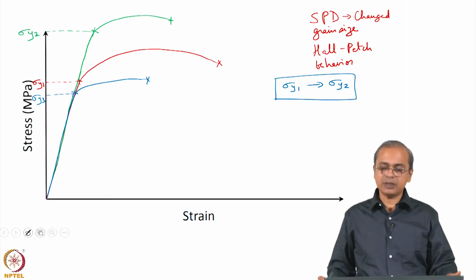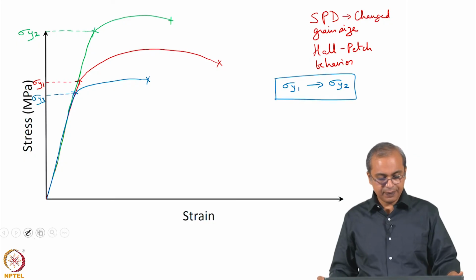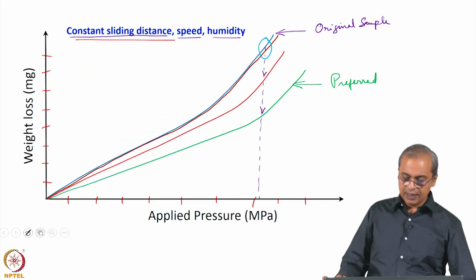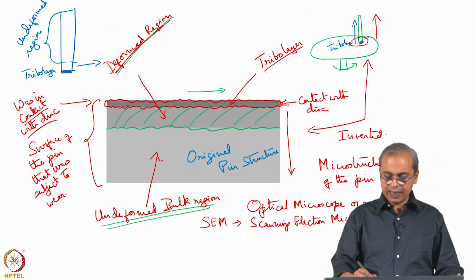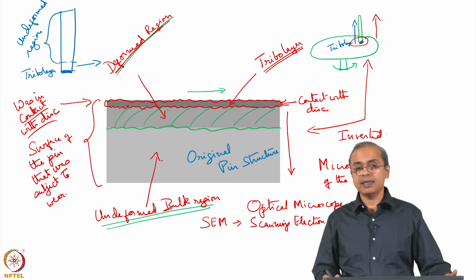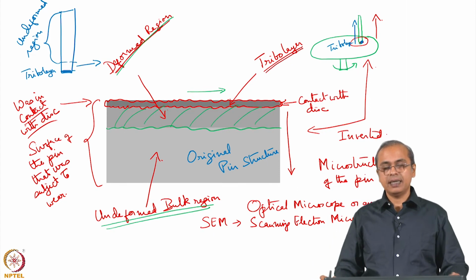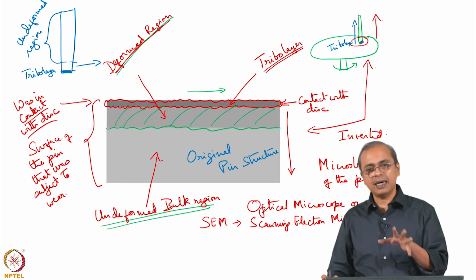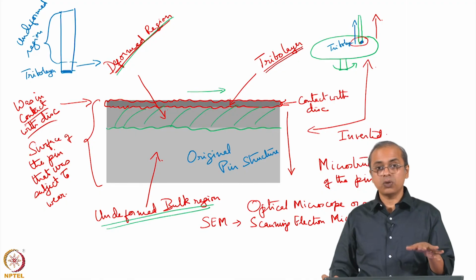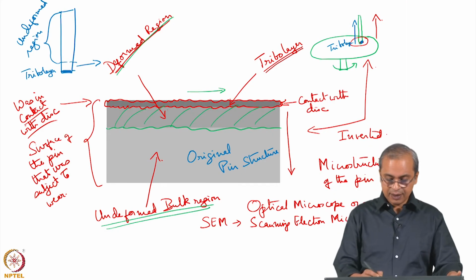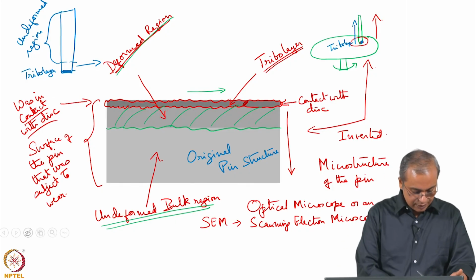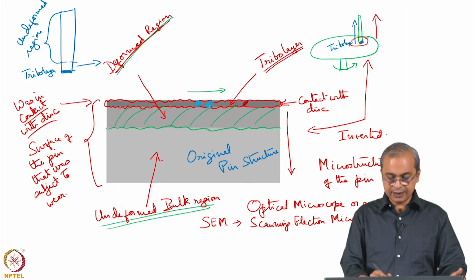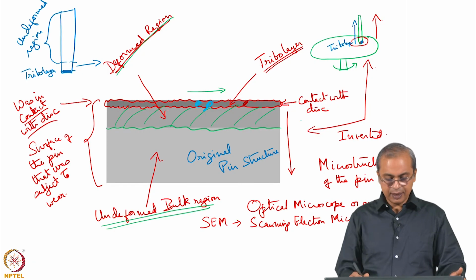And so, people have studied those kinds of systems, and typically the reason that they give, if they see this kind of a situation, has to do with the state of your tribo layer. The tribo layer, which is this oxidized material, really depends on the condition of that oxidized material. If that oxide is extremely hard and also very abrasive, then this oxide layer that you form, which has a lot of oxide particles, will also dig into the deformed region.